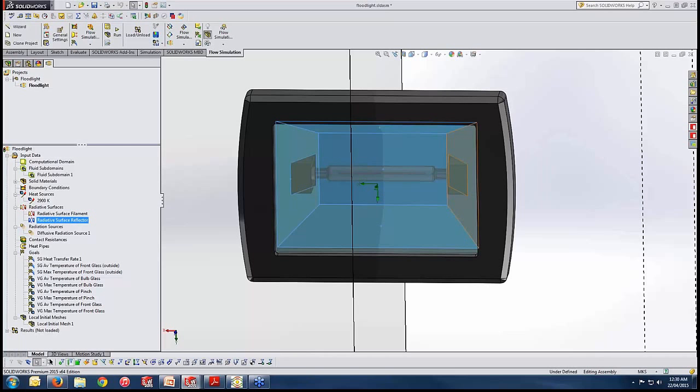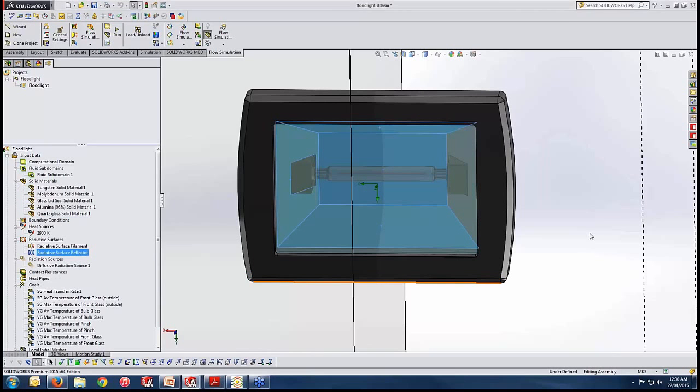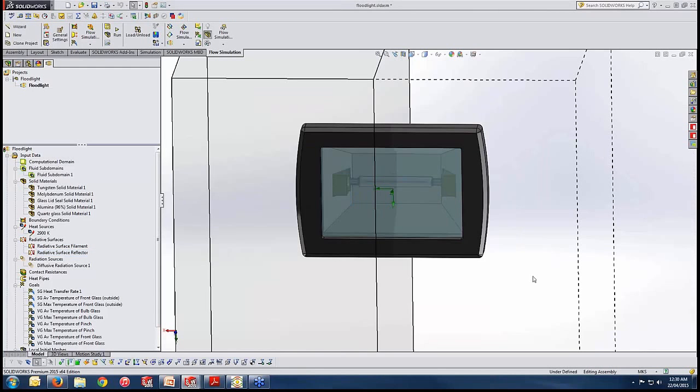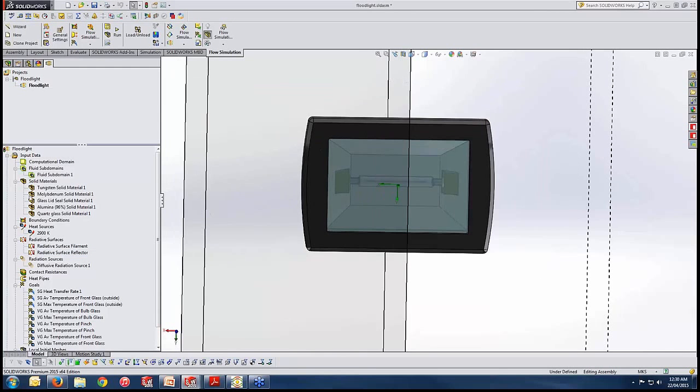All right, so we have done this step as well, and we are now in the business of saying what other solid bodies I have in my model. If we'd like to assign any other solid body, again right click and insert solid material.